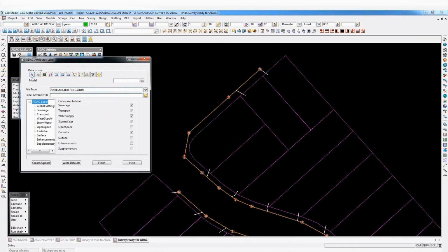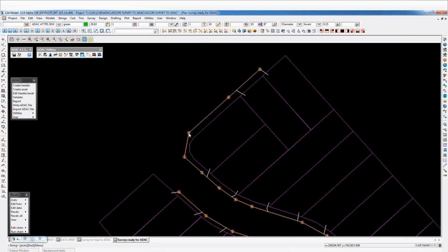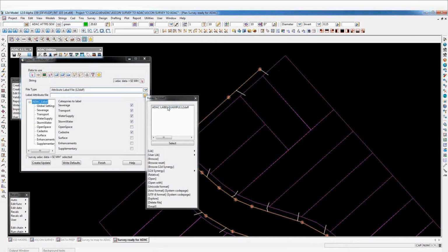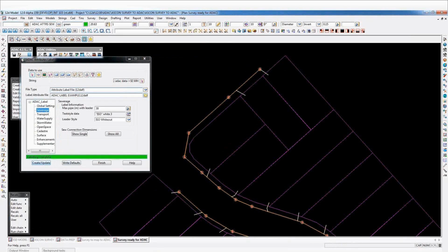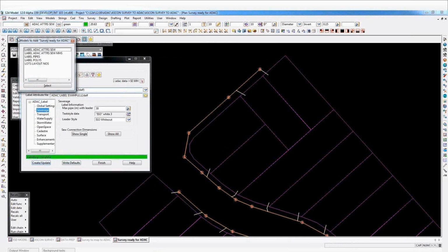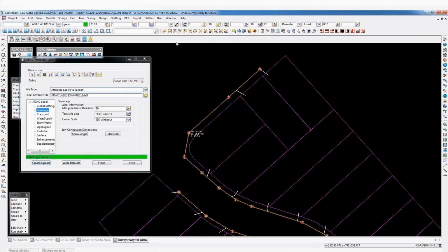You can run the labels here. We'll just do a couple at a time. So we're going to pick our manhole. We're going to label. We're just going to do series, so you can just do the asset or the category that you're after. We can go right or create. So add in our labels, label manholes.